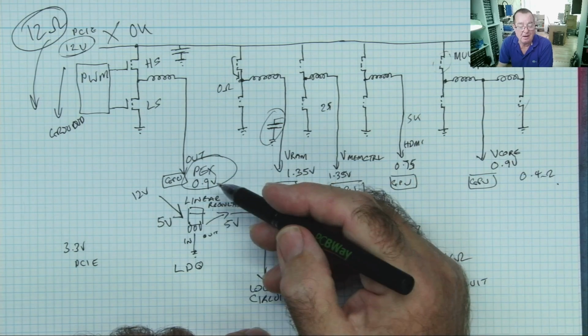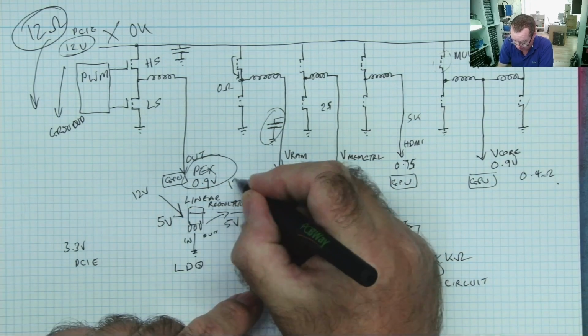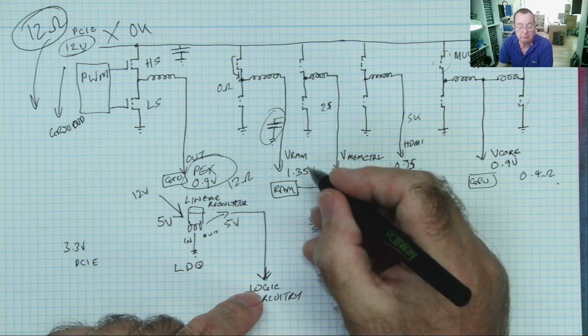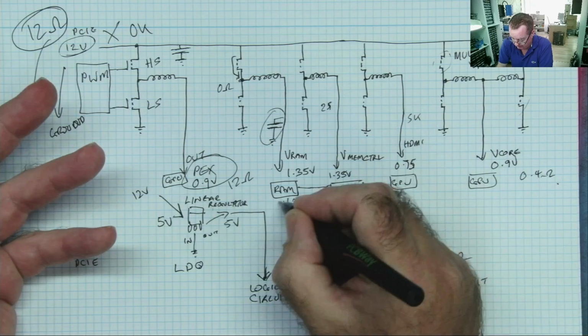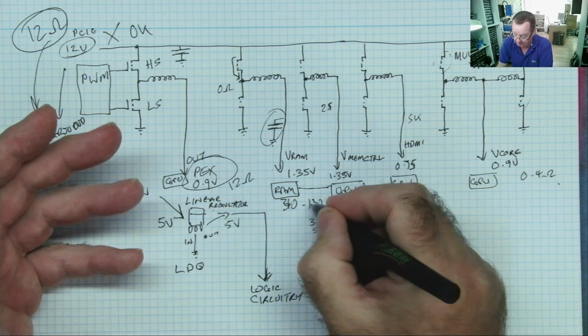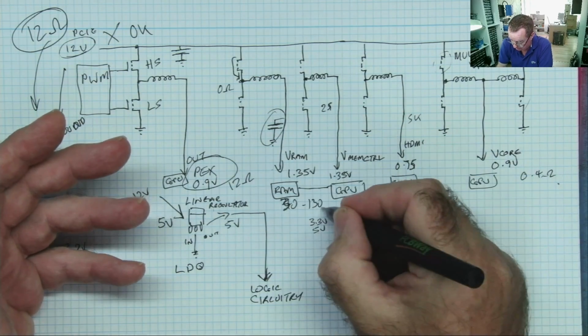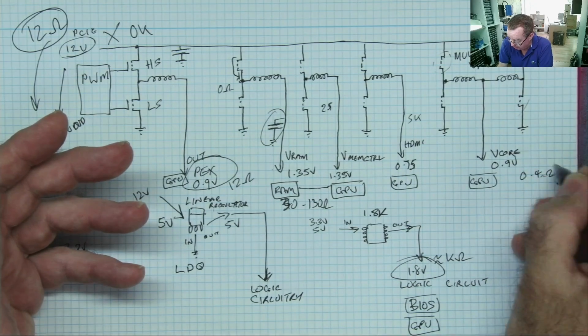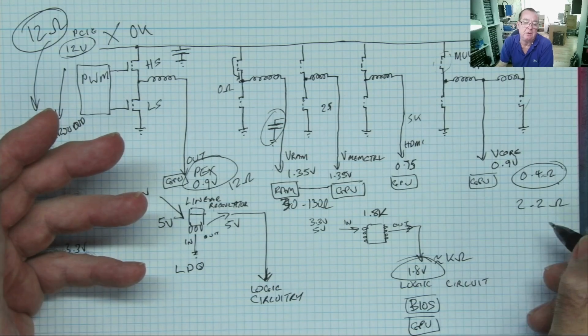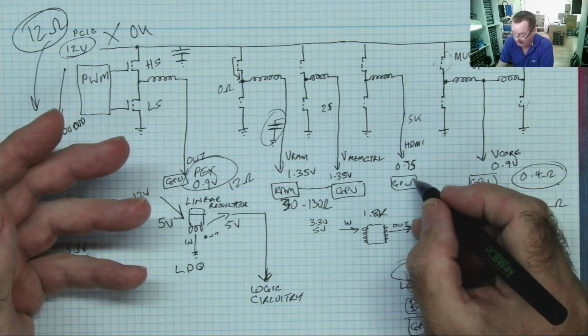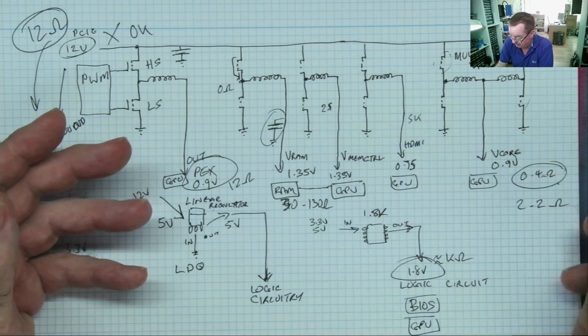Now, quite likely PEX will read about 12 ohms. RAM could be anywhere like 40 to 130, maybe 30 to 130, maybe outside of that range, ohms. GPU about 0.4 up to maybe a couple of ohms or so, depends on the GPU. This reads high, I've told you this, maybe in the kilo ohms.